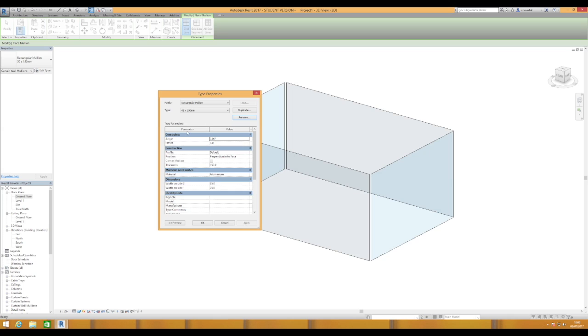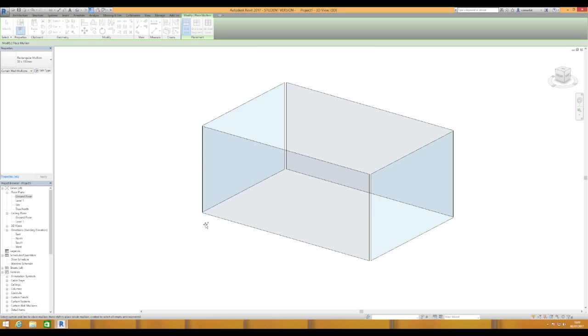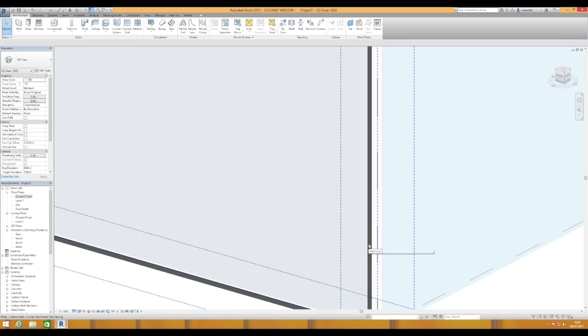So I've changed its name, so we now better change its dimensions. We'll leave the 150 the same as it was because it's 45 by 150, but the width on one side is going to be half of 45, 22.5, and the width on the other side is going to be half of 45, which is 22.5. So these two widths added up give the total width of the rectangular mullion. If I click OK to that, and then click on the edges of this curtain wall that I established here, we'll just use this one for starters, we can see that we've got these mullions being displayed.